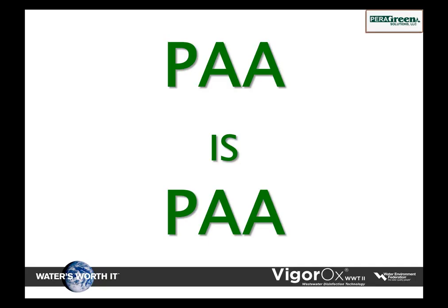Can you flip? Our next slide, pretty simple slide, PA is PAA. If you remember, I talked about 12 and 15% concentrations. I've done side-by-side studies with Solvay's 12 and 15% PAA in field applications. The data we've returned demonstrates there's zero impact between the 2 different concentration levels for rate of reaction or efficacy.